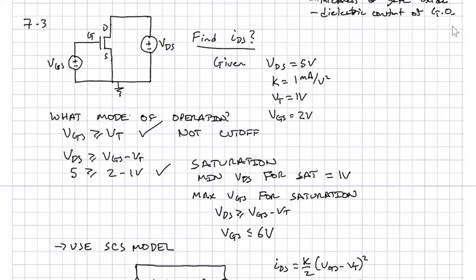There's nothing that can change. When we have ideal voltage sources on VGS and VDS, it's clear that that current's going to flow, and the mode of operation is trivial. We just subtract the voltages appropriately. But if we have more complicated circuits, then you really need to check: assume the mode of operation, find an answer, and check it to make sure that your assumption is consistent with your answer. And if you do that, you will always get the right answer, assuming you do the math right.